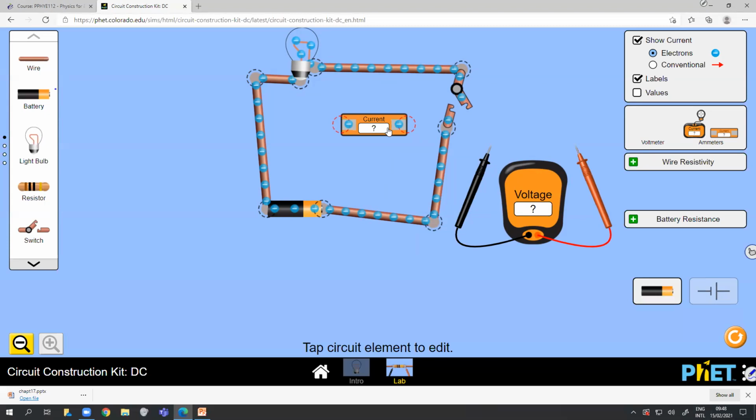So that means it is a series connection. We talked about this with capacitors in series and capacitors in parallel. When you connect two capacitors in series, you connect end to end, so the charge that flows through one capacitor will flow through the other. It has the same charge. Likewise, if you want to measure the current through this bulb, the same current should flow through the ammeter as well. So it should be connected in series.